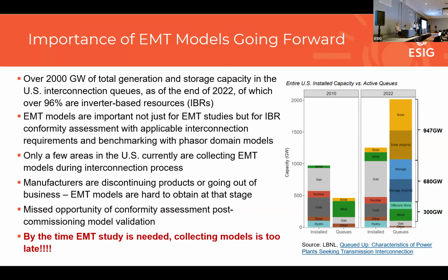EMT models are not important just at the time when you need to do EMT studies, but as I mentioned, with the example of previous NERC disturbance events, they may help to detect issues early during the interconnection process, and you can also use them for benchmarking PSCAD models. So you have 2 sets of models that you can benchmark against each other.